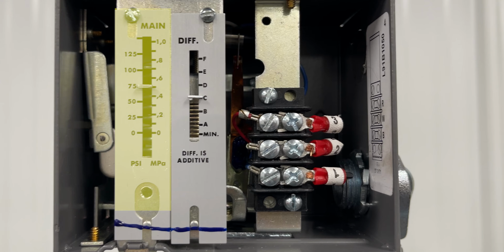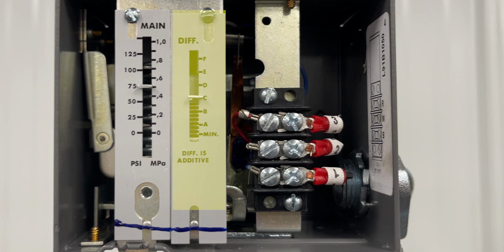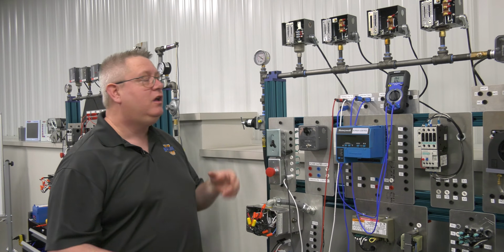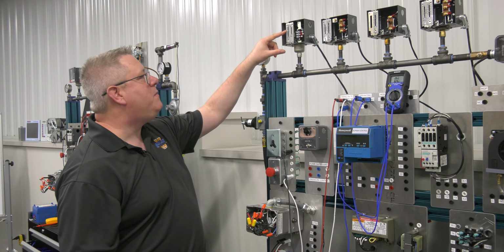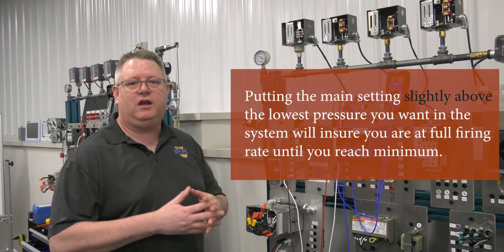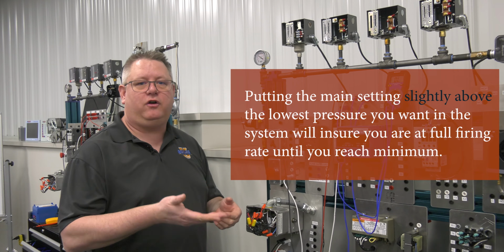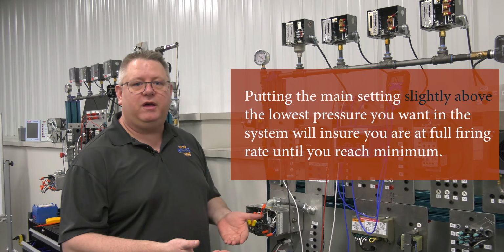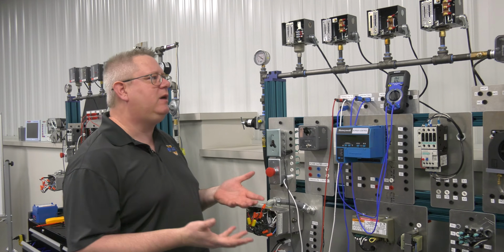One setting is the main setting, and the second is a differential. And it says on here that the differential is additive. And what that means is that at the firing rate set on the main, that control will be commanding the mod motor to go to the high fire position. So typically I'll set this main setting slightly above the lowest pressure that I care to see on my system, because that's going to ensure that we're at full firing rate until we attain that minimum and a little bit beyond.